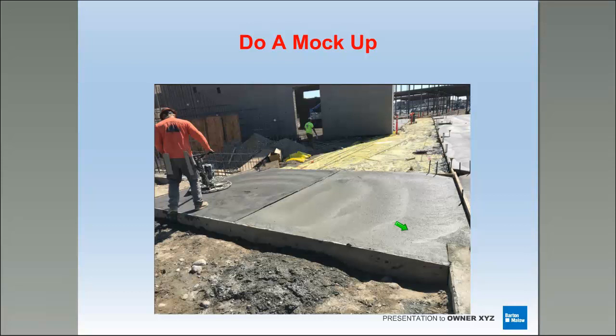We talked about this. Always do a mock-up slab. You can see the size of the slab, not real big, but they're going to do a mock-up. If I were polishing this building, I'd want to come in here and drop a polish on this and see how it cuts. We want to do our due diligence to make sure everything's working. Typically, I would do a larger mock-up with the machinery I'm always going to use. He's got to walk behind on it. I get it. Try to make the mock-up as representative as what you're going to pour with your equipment. If you're using a laser screed, do a mock-up that can handle the size of a laser screed.